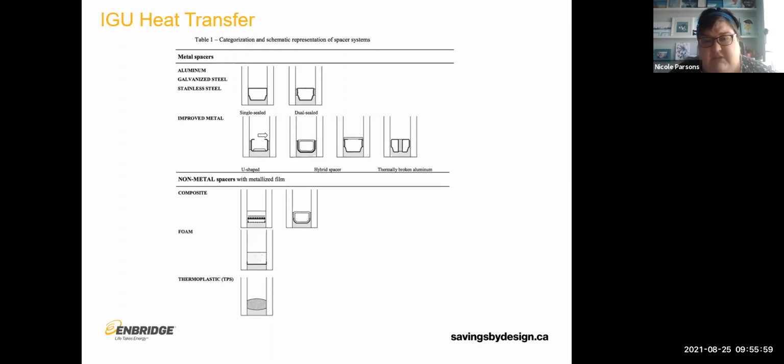This is still a thermal bridge between the two pieces of glass, but it's not a complete one. And this is a very similar situation where they have a plastic top on it. So aesthetically, it looks a little bit nicer, but it performs the same. You can also get hybrid ones where you have metal and then maybe plastic all the way around inside.